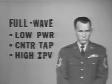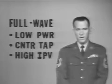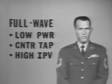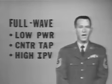It is double the output voltage. Now this means that rugged diodes and rather large transformers are needed to supply high output voltages. There is a definite need, then, for a rectifier without these limitations. The bridge rectifier meets this need.